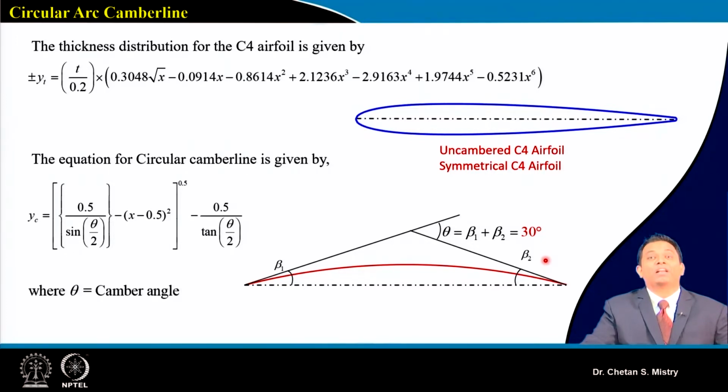When I say metal angles, do not forget we have discussed we have our flow angle plus or minus incidence angle, and our flow angle and deviation angle. That gives us my entry angle and outlet angle, which we have defined as our metal angles. So these are my metal angles.